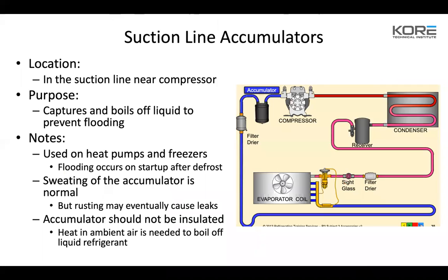Suction line accumulators. Okay, so let's talk about suction line accumulators, because I see this being a need that we're finding. Anytime you guys have more space or volume in your evaporators than you do in your condensing unit, as far as tonnage, we need to put suction line accumulators, or we need to size with suction line accumulators. We have a lot of Mavericks and such that we're running like a 4-degree superheat. Well, if we're running a 4-degree superheat, we're flooding the coil.